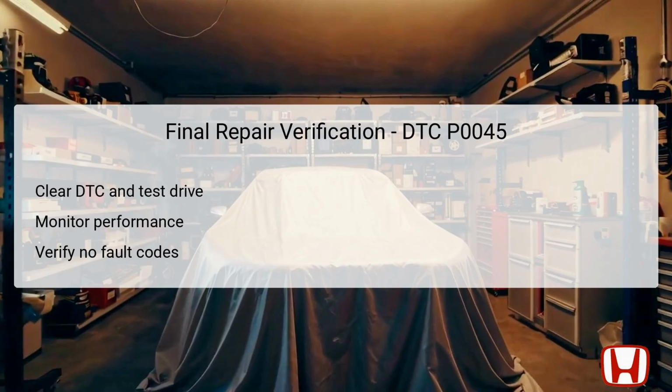During the test drive, monitor for any unusual behaviors, such as delays in turbo response or fluctuating engine performance. It is critical to ensure that no fault codes reappear following the test drive, as this would indicate the persistence of the issue. Verification of successful repair encapsulates both clearing the DTC and confirming that the engine operates smoothly, reaffirming that the repairs made were effective.